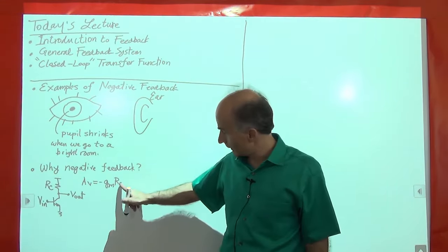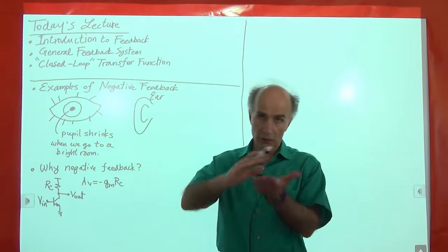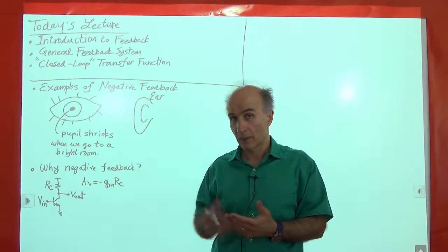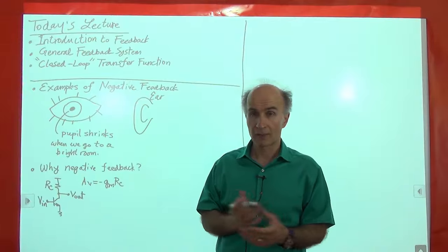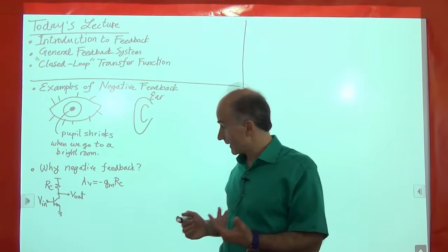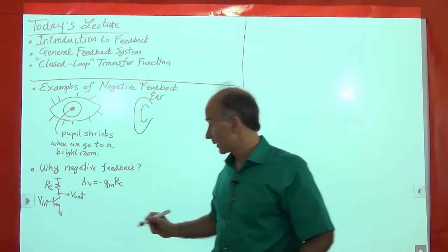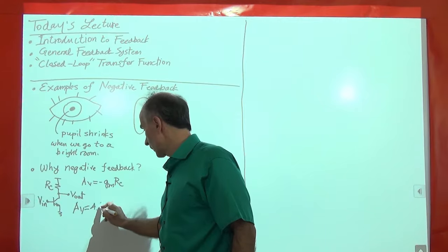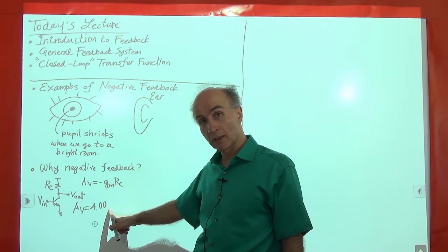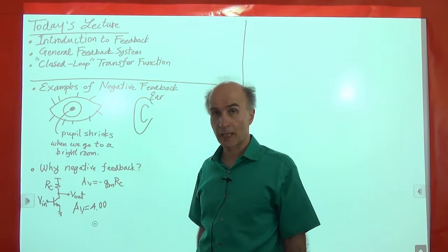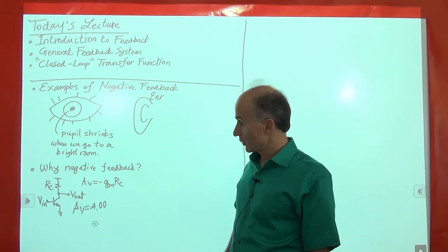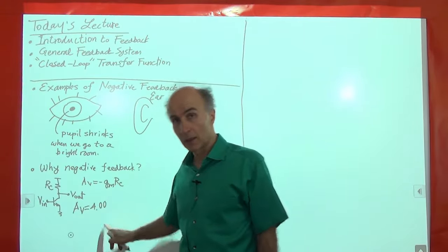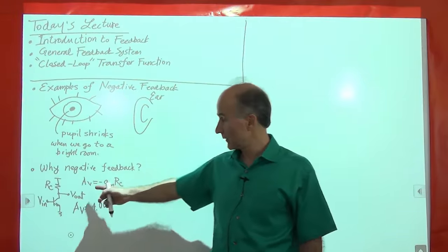Why? Well, for example, this resistor, however we build it, on a chip or as a discrete resistor, has some variability. With temperature it changes, from sample to sample it changes, so it's never that accurate. So for example, if an application requires a gain of 4.00 to such precision, there's no way that this can give us that amount of accuracy. Okay? So we have many examples. There are many interesting circuits that do need such a precision, and for those we can't use something like this, right?